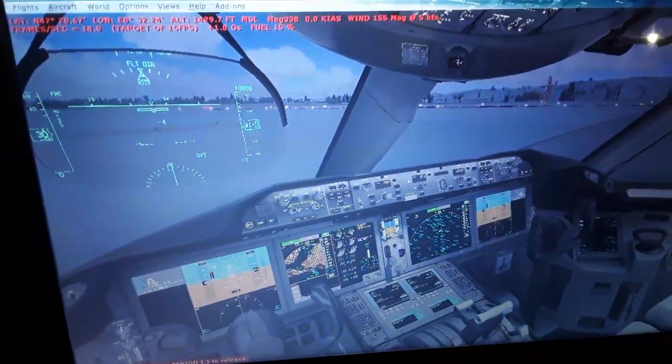The flight management computer is going to calculate automatically the center of gravity of the aircraft during the whole flight. As we burn fuel, the center of gravity is recalculated. Also, we change the attitude of the aircraft in flight, and this is done automatically by the flight management computer. Also the mean aerodynamic chord position of the aircraft, and also the angle of stall. Also the horizontal trim stabilizer position from takeoff, climb, cruise, descent, approach, and landing.